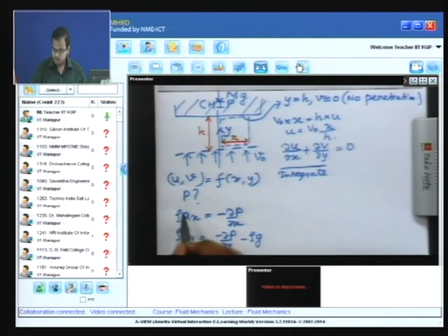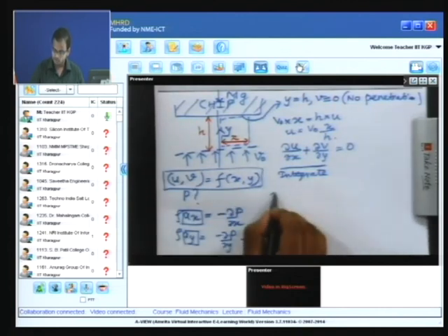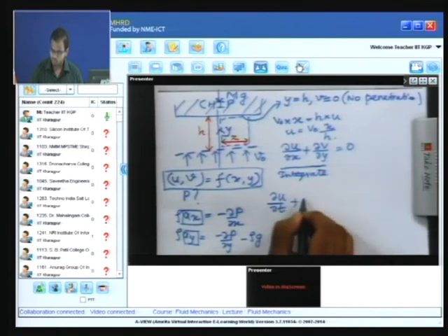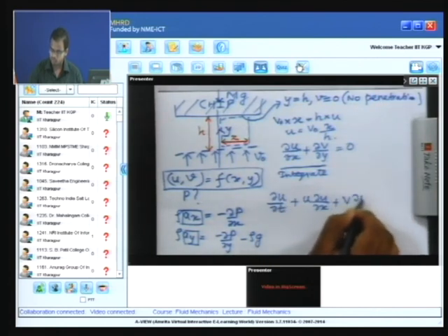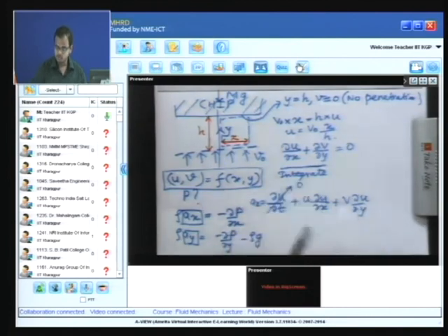Now, Ax and Ay are to be found out by using the flow field. For a steady flow, Ax is this, for a steady field this will be 0. Now, these two you can evaluate using the information that you had just obtained. Similarly, you will obtain what Ay is. From that you will integrate this equation once to find out p, and to find out the constant you will make use of this condition, this equation.